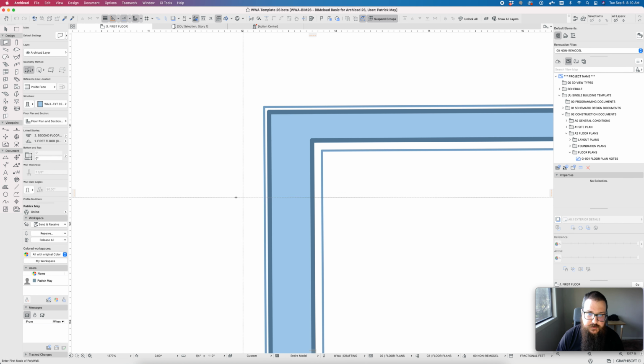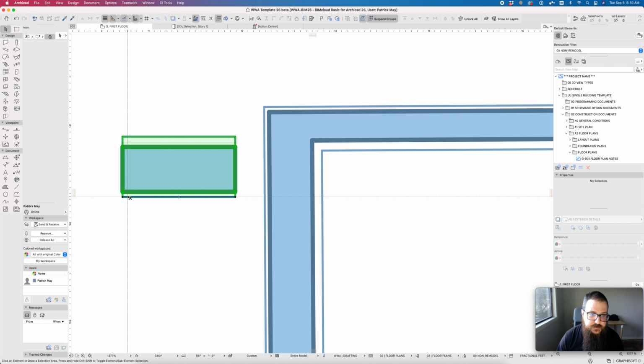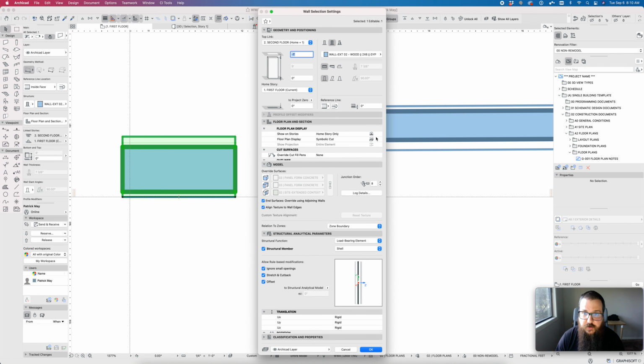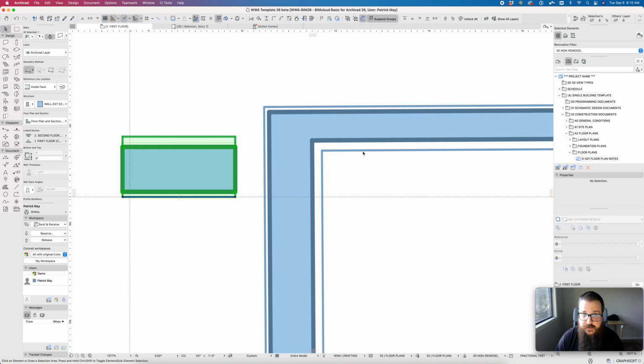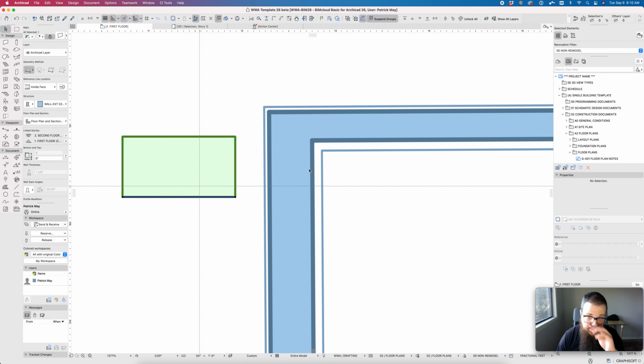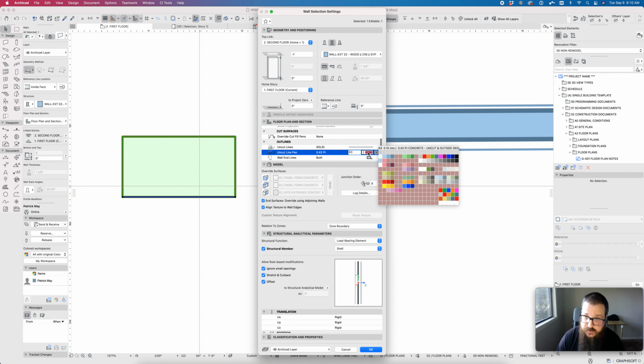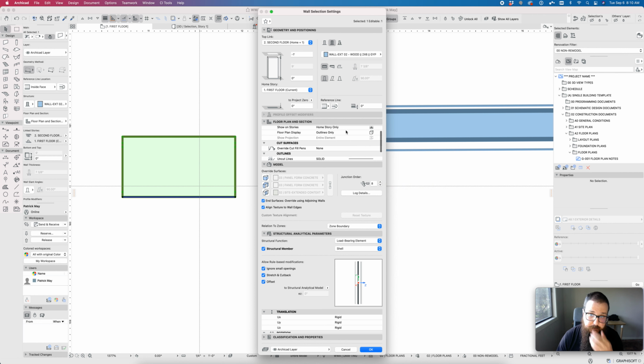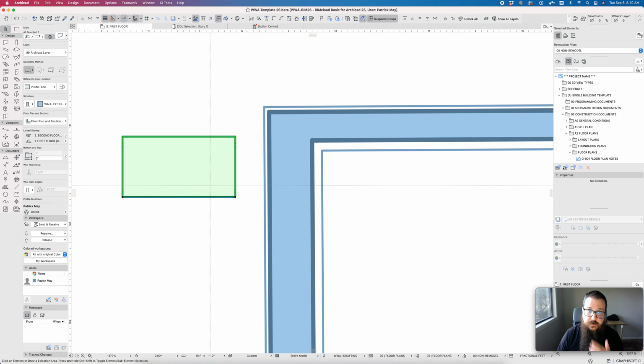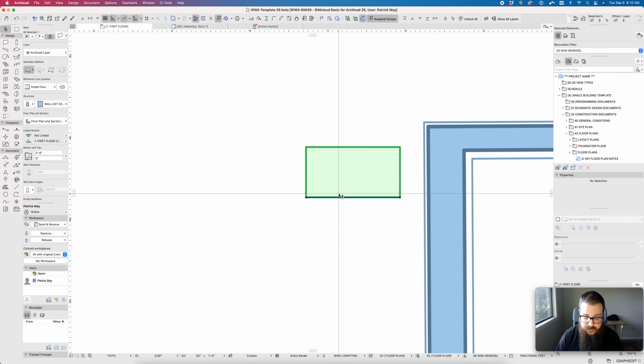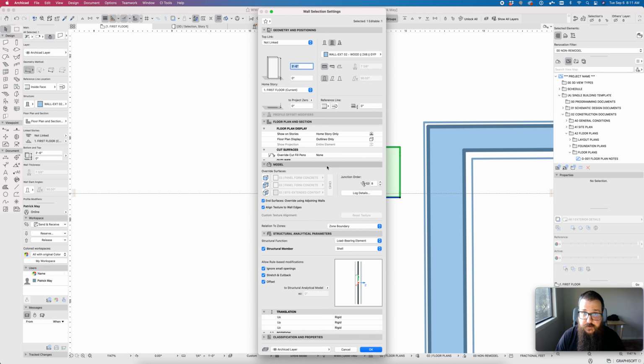Now if I had maybe a partial height wall or something that wasn't linked to those story settings, maybe like a low guardrail type situation or even a curb wall, I might want to first show that as outlines only. What that's going to do is show just the outline of the wall. That also unlocks a few other wall settings here that we don't have by default. So the uncut pen was hidden when it was set to projected with overhead or cut only. And now I can say that this wall maybe isn't linked to my story settings and it's only a 3.5-foot wall if it's a guardrail type situation. So that is one situation where you may need to unlink or have an independently set wall height.